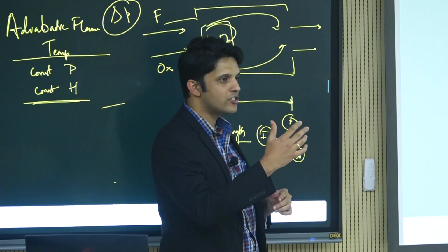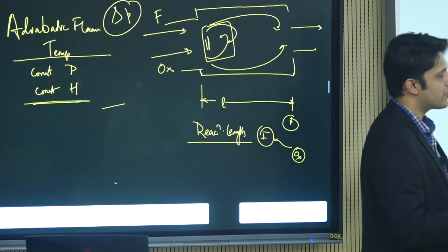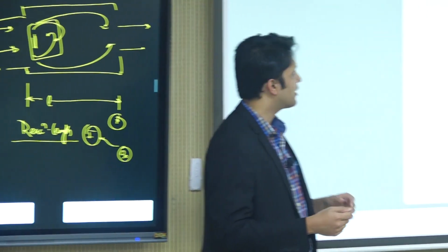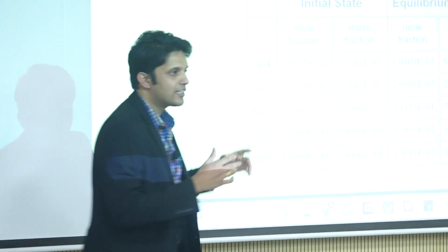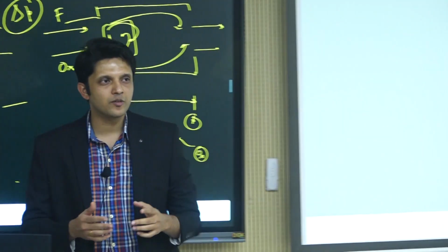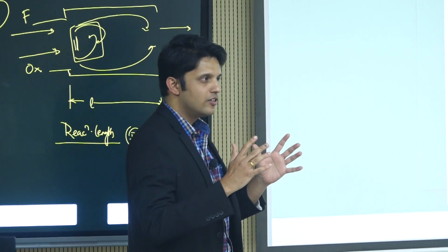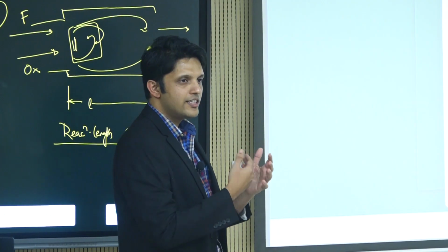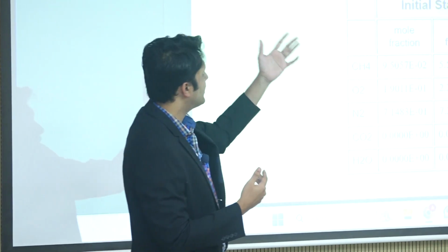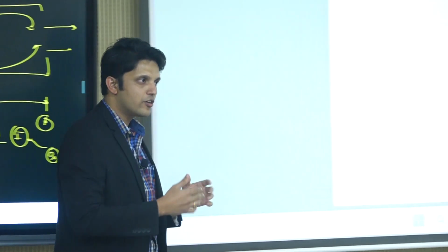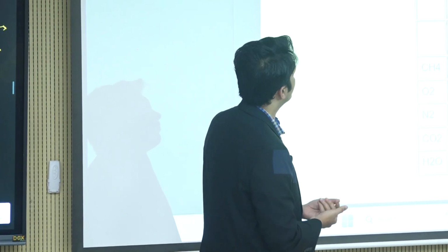The flame temperatures are way higher than what we expect. What we measure is exhaust gases, where you have a lot of heat loss, heat transfer to the surroundings, and after that you are probably measuring 700 to 1200 degrees Celsius. But at the flame front, your temperatures are at 2300 Kelvin, 2200 Kelvin for typical hydrocarbon fuels. So if your combustors or structures get in touch with these flame fronts, you can imagine the amount of heat transfer taking place, because these are at 2300 Kelvin and your structures might be at 300 Kelvin ambient condition. So a lot of heat transfer will take place.